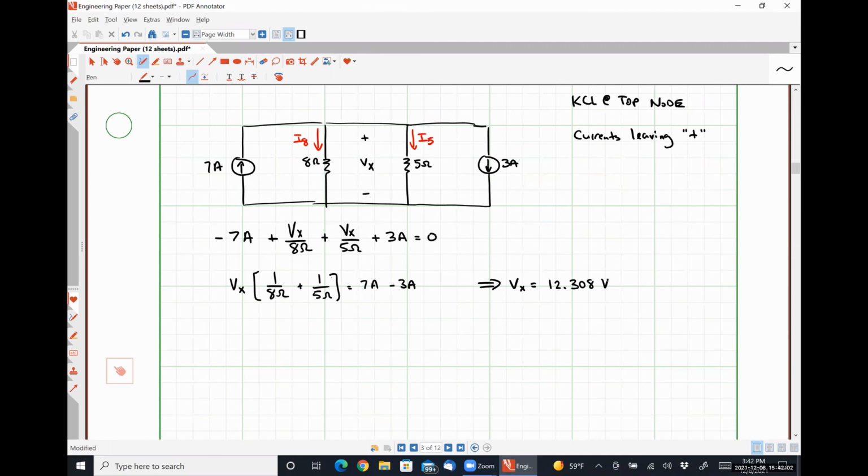Here's how we can use Kirchhoff's current law as well as Ohm's law to analyze what's called a single node pair circuit. In a single node pair circuit, all of the elements are connected in parallel. And so, in my opinion, applying Kirchhoff's current law to a single node pair circuit is usually how you should start off your analysis. Okay.